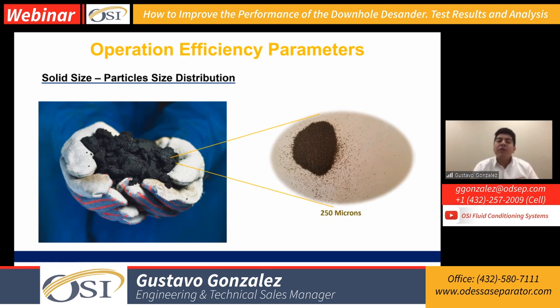Get a sample of the sand that is inside your pump, or if you have a sand leaf or any device that helps you capture some of the sand when you get those teardowns on an ESP, take the opportunity to evaluate the particle size distribution and how that sand looks. So this is how the sand always looks when it's mixed with the oil.